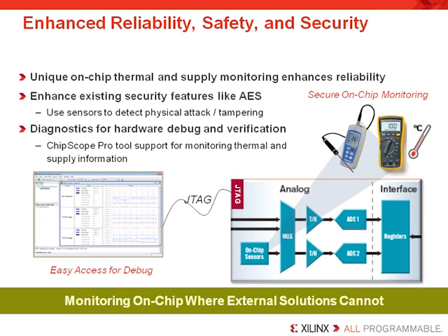The power supply and device temperature information of the chip, including the off-chip signal monitors, can be accessed via the JTAG interface or through the FPGA fabric. These signals can be monitored with the ChipScope tool, even without instantiation of the XADC core into your design. The XADC device operates in a predefined mode called the default mode that monitors on-chip temperature and supply voltages.